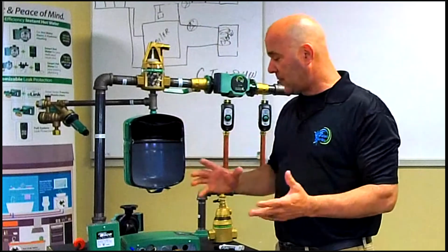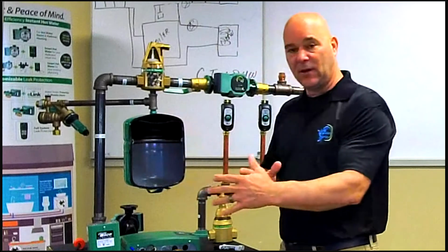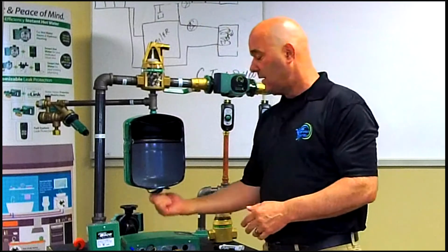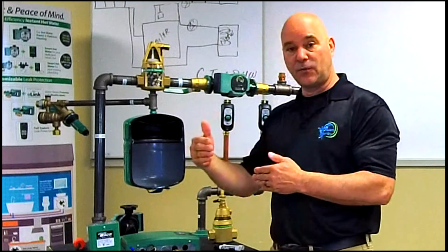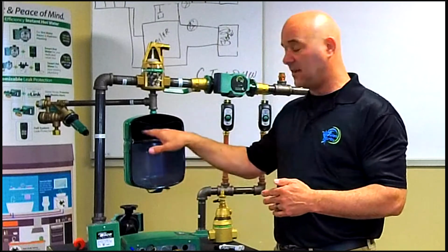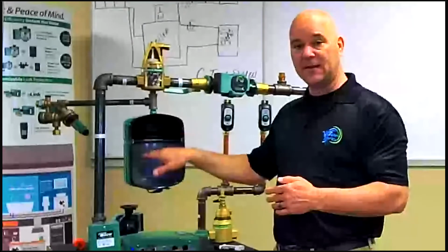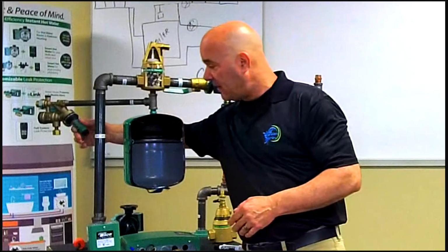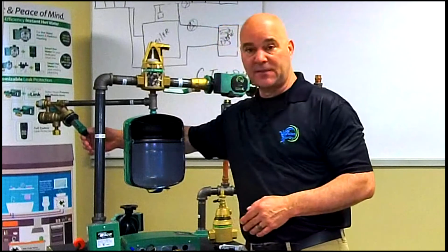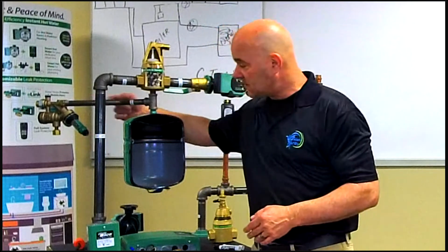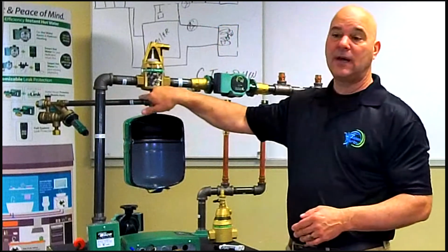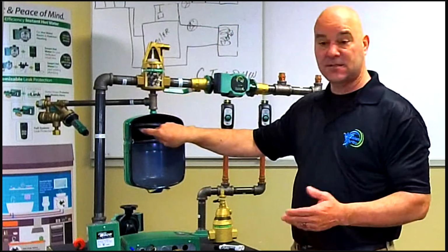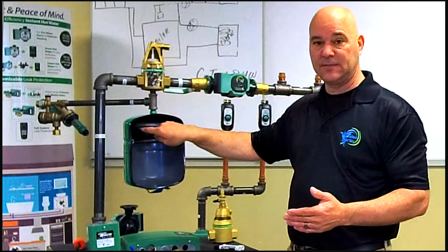The only correct way to do this is the expansion tank would be off the system. I would go down here to the air Schrader valve, and I would put in an additional 4 PSI to get 16 pounds of air on the bottom. Then I would go to my feed valve and make the adjustment, putting 16 PSI of water on the incoming water side. And that would allow the expansion tank to still remain in the proper position.